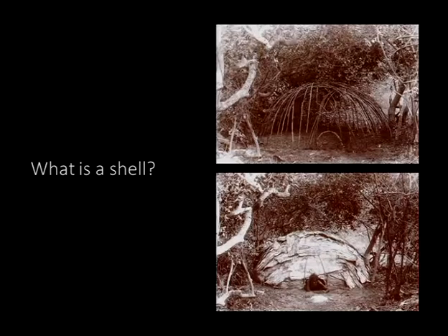So what is a shell? It's interesting to notice that I found in a book about Australian Aboriginals this type of constructions. So this idea is that you just bend some pieces of timber and then you clad them. So somehow you are creating a structure. Nowadays we would say this is called active bending. So it's resisting and it's taking a specific form because we bend that shape, and all of them together they create a dome, which is rather thin compared to a normal beam.